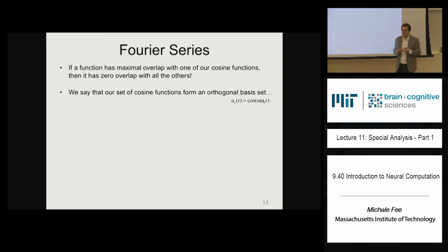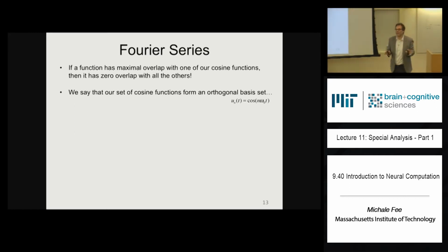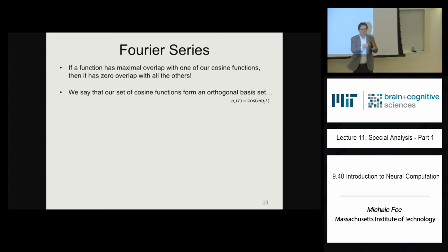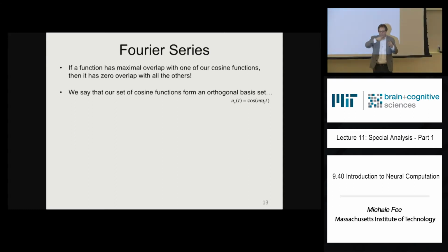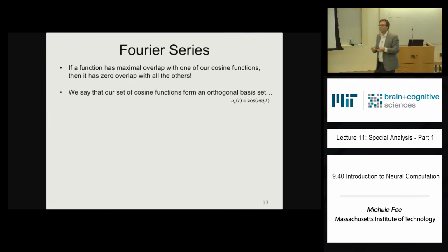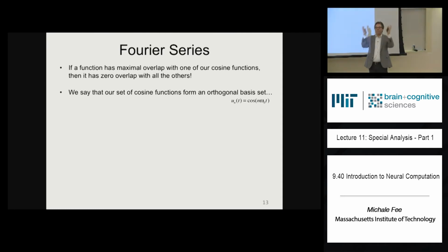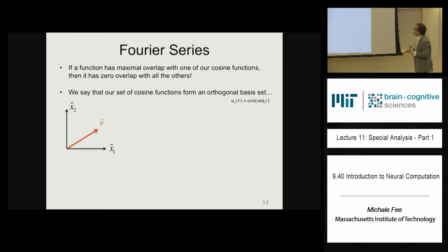Okay? That's it. That's all spectral analysis is. And the particular views we're looking at are projections onto different periodic functions, okay? Cosines of different frequencies. All right? And what you find is that for periodic signals, there are certain views where something magically pops out and you see what's there that you can't see when you just look at the time domain. Okay? All right.